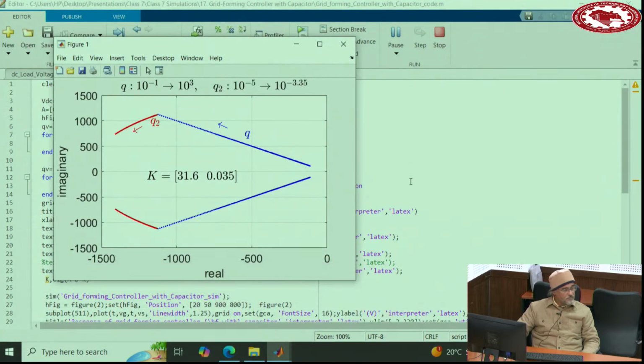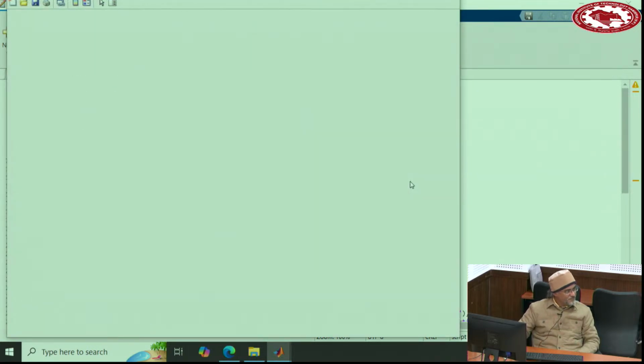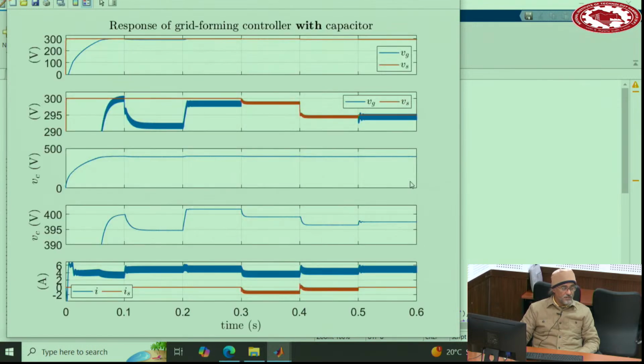So first it makes few metrics, properly selecting the pole location, and then it runs the simulation. Use the Ackermann formula to get K1, K2, K3? No, LQR to get it. We never run Ackermann anymore. Yeah, LQR. LQR to get these gains K1, K2, right, exactly. But first we need to select the pole position, so where we want them.